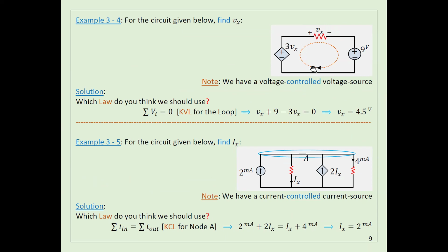So let's apply Kirchhoff voltage law to get a relation. To make it simple: Ohm's law gives you a relation between current and voltage on one element. Kirchhoff current law gives you a relation between currents at one node. Voltage law is going to give you a relation between voltages in one loop. So that's what I'm going to apply now. Here, Kirchhoff current law is not going to help me because it's just the same current. It's just one current.